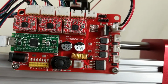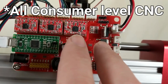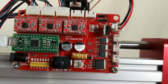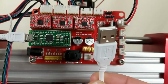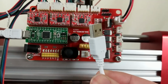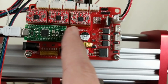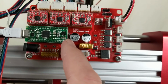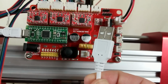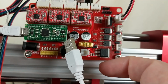So all in all, it's a pretty decent little cheap control board, and just like all CNC routers, for some reason it's still the paradigm that you have to keep it connected to your laptop, which is running a dedicated controlling software that's going to be sending the G-code line by line, or maybe in packets of 10 lines or something like that, to the controller here. But if this gets unplugged from your computer mid-job, then the whole job is ruined.